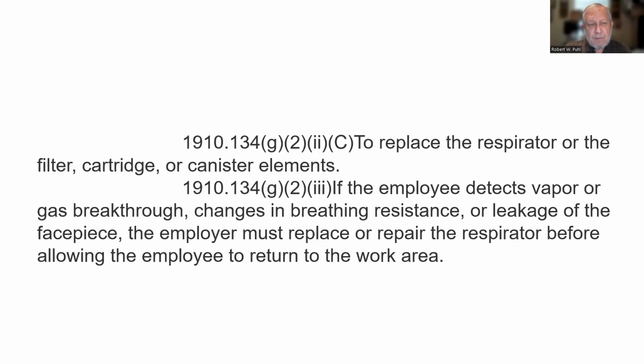If the employee detects vapor or gas breakthrough, changes in breathing resistance, or leakage of the face piece, the employer must replace or repair the respirator before allowing the employee to return to the work area.